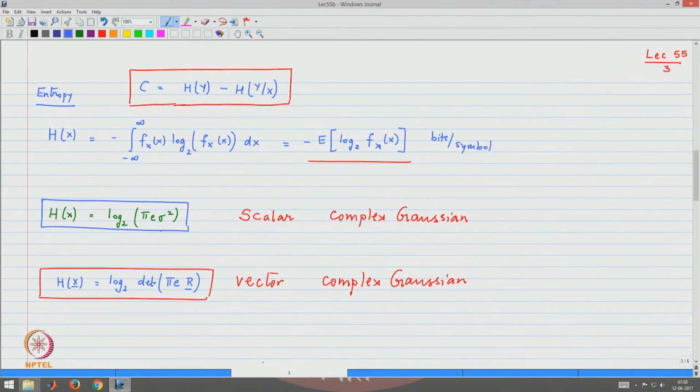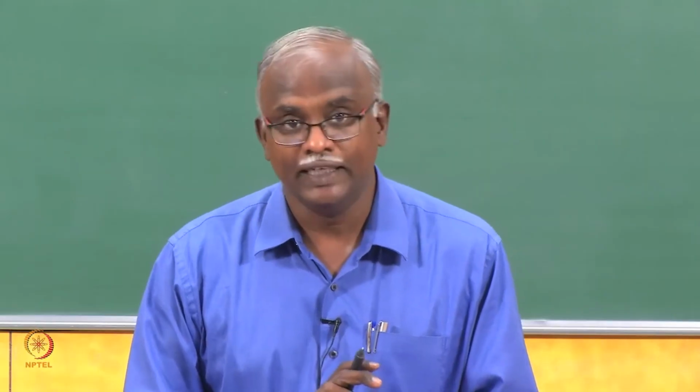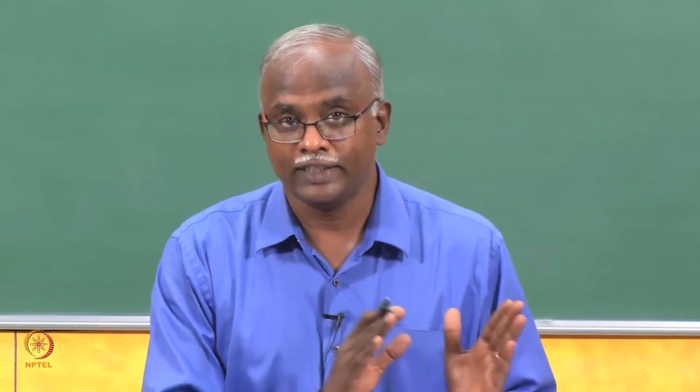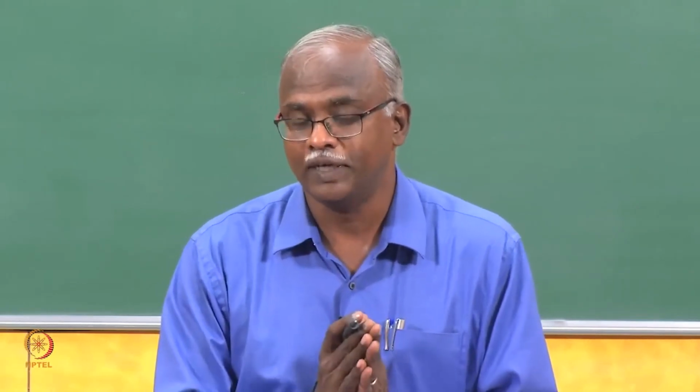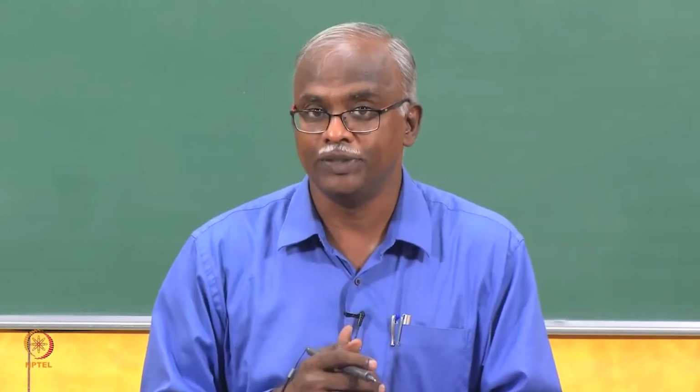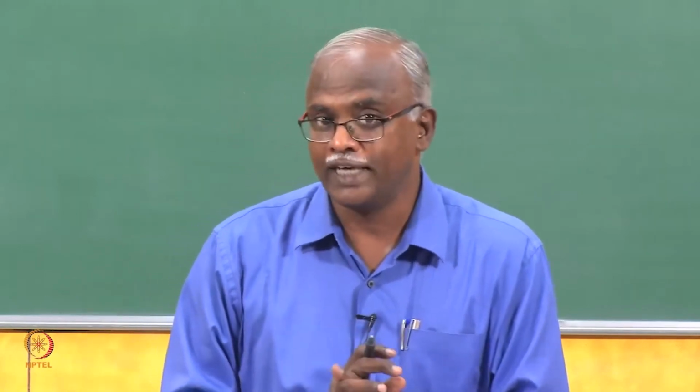Given this framework, we are now trying to look at the case of capacity in the context of a system where the transmitter does not have knowledge of the channel, because in the case where the transmitter has knowledge about the channel, then we can do the singular value decomposition of the channel, which creates the eigen decomposition and then the parallel channel transmissions that we can do by using pre-coding at the transmitter, followed by the post-processing at the receiver.